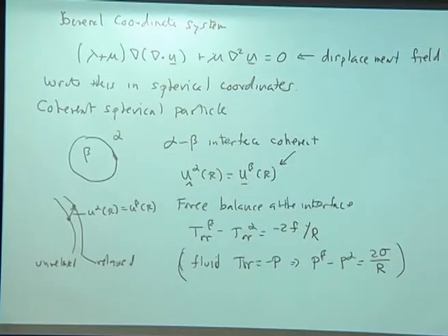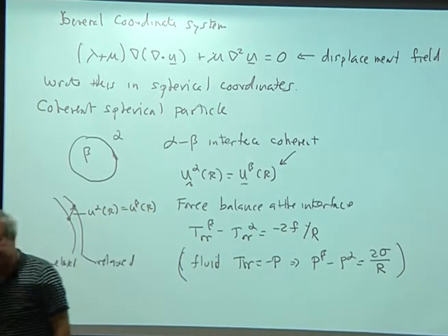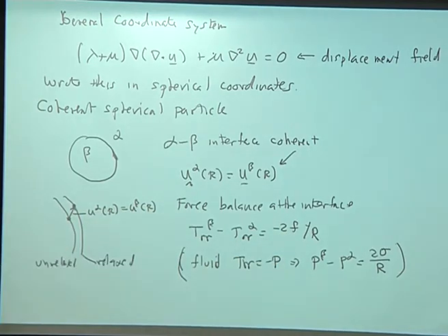And so these large stresses might be affecting the stress field in the system. In fact, if you measure the lattice parameter of nanoparticles, they're not equal to the lattice parameter of a bulk material because of this effect here. Okay, so they can become important as well, but typically they require relatively small objects. So we'll put that in as a source of stress. Okay, questions?